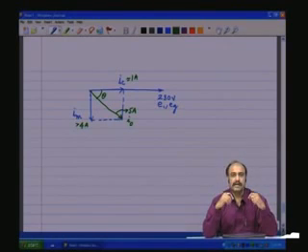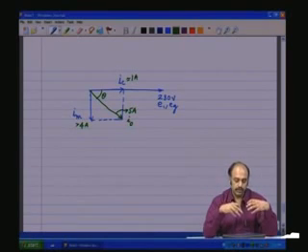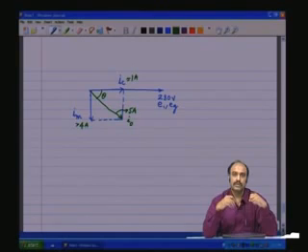Now, all practical transformers will have some flux which does not link the other coils which are in the core path, and they are called the leakage fluxes. And we will see how we try to incorporate the leakage flux component into the equivalent circuit model to have a much more complete picture of the transformer. Further, we need to also include the copper loss component into the model. This we will see